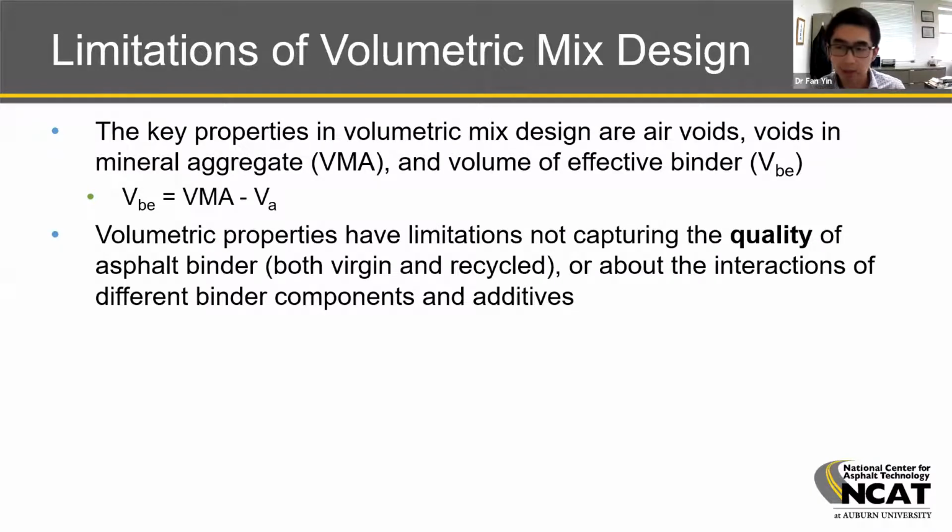But the VBE is a volume parameter. It gives us an indication of how much asphalt binder we have in the mix, but it does not tell us much about the quality of the asphalt binder. We may argue that this is where we have the binder specification. I know in the Caribbean countries you use a penetration grading system, and here in the US we are using the Superpave performance grading system.